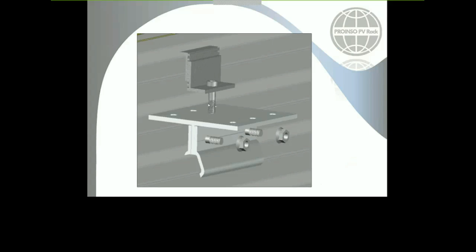to avoid distortions. And with this method, we are now working without any rails in South Africa, so you don't need any rails to put the modules now. However, there are cases where rails will be required for any reason, okay, and they would obviously be fixed to these holes. But in the cases that we don't need any rails, the clamp is just going to be fixed directly, okay, to the PV clamp.